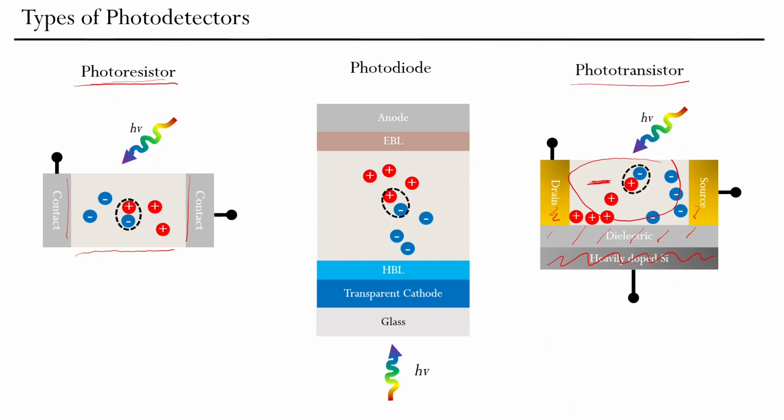So we can improve noise characteristics, and we can increase the resistance of this active layer compared to what it would be without any gate electrode. That could be a good option to have this possibility to modulate characteristics of this photodetector.